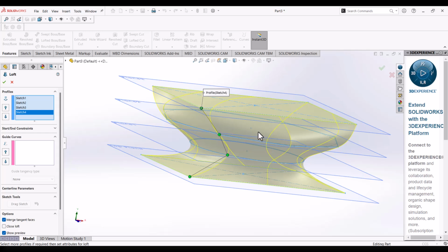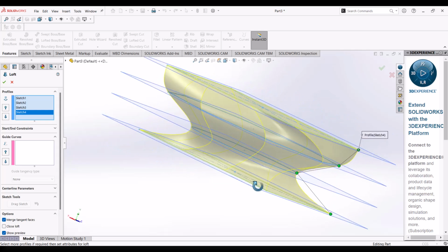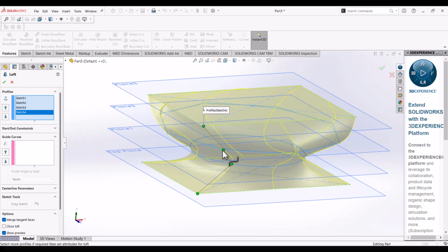Every section or every cut in the mouse has a different shape. It's very curved, so if you use a single plane and a revolve, it will give you something circular, but a mouse has a curved surface.